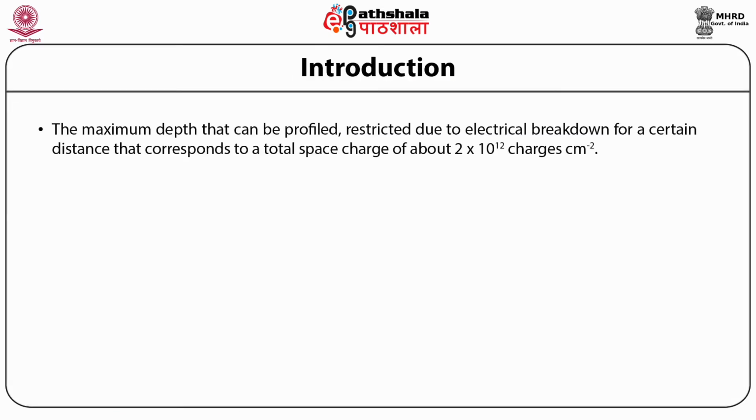The maximum depth that can be profiled is restricted due to electrical breakdown for a certain distance that corresponds to a total space charge of about 2 × 10^12 charges per centimeter square. Furthermore, the CV profiling of low bandgap materials and materials like InP is difficult.